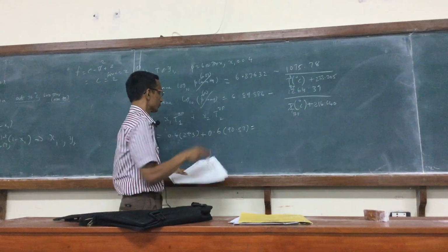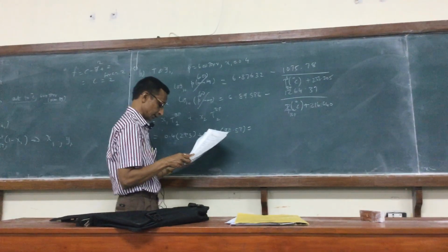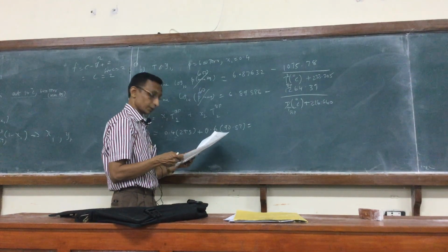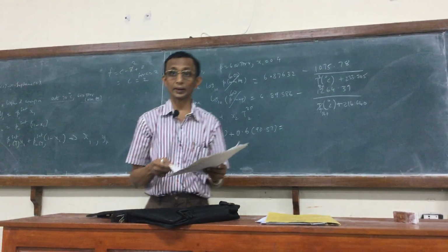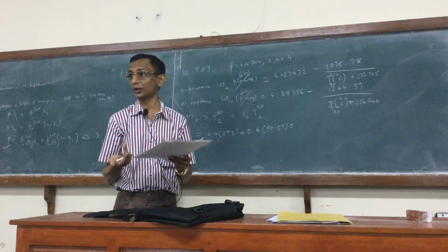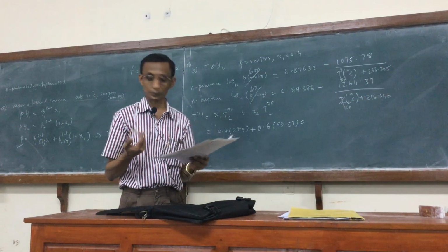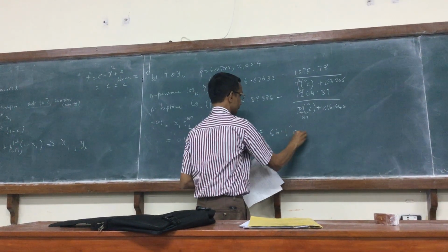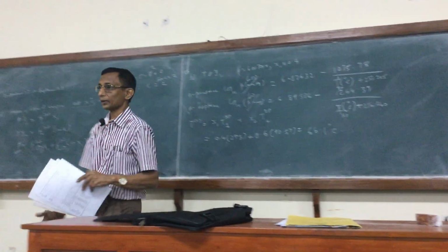And if I put 600 in this, I should get 90. So these are the pure component boiling temperatures for pentane and heptane, and those are available to you. So you cannot say that the information is not given, if you know how to calculate it from the Antoine equation. The answer I'm getting is 66.1 degrees centigrade. So that is what you have to do.